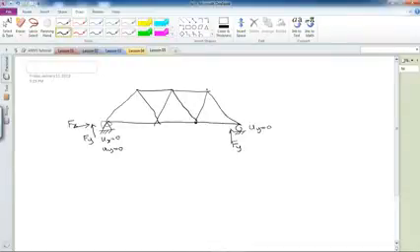In order to avoid symmetry in this truss, to make things a little bit more complicated, I'm going to apply an Fy. Or let me change these F's into R because they are reactions, and R is going to stand for reaction. I'm going to say reaction Rx1 and Ry1, and Ry2 in order to avoid confusion. I'm going to call this one Fy, and on the node here I'm going to apply an Fx. So we're going to have an external load of Fy applied on this node, and a load applied in x direction on this node.